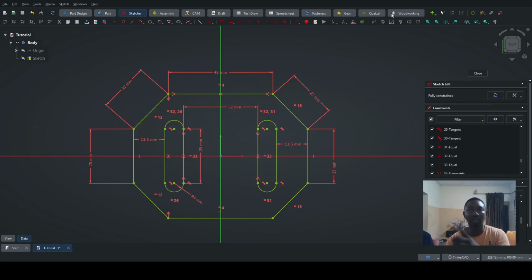If you want yours to look like that too, you go to preferences, you go to workbenches, you change it here, and you change this to tab bar, then it will look exactly the way mine looks like. You get that? So I'm not changing anything, and I think I'll teach you other things now as I have time to. So let's stop this now.